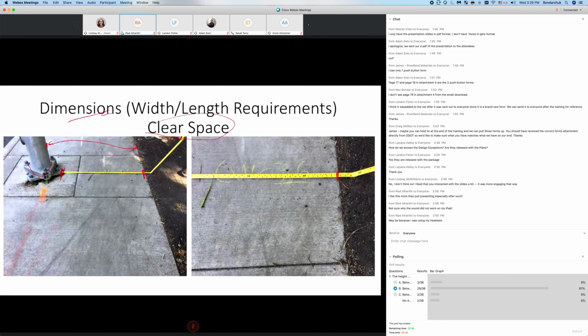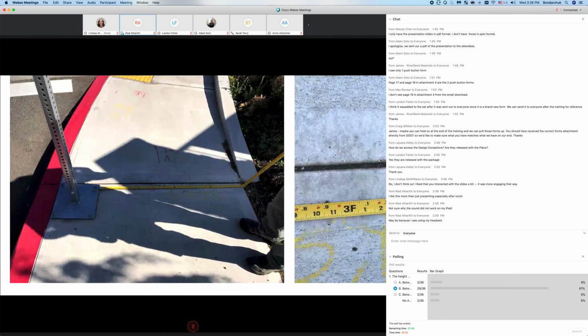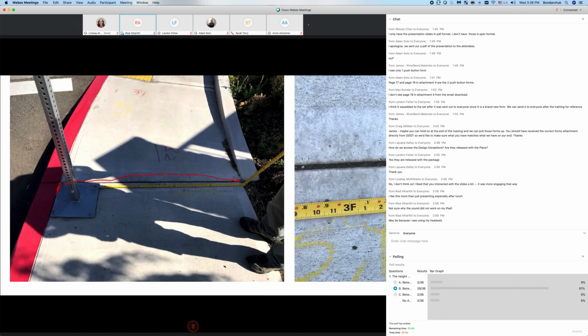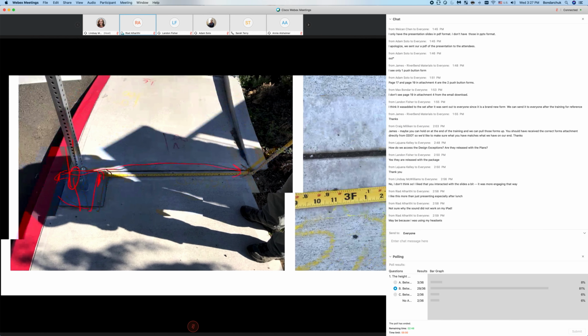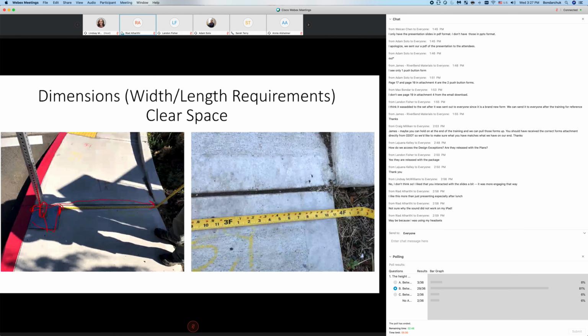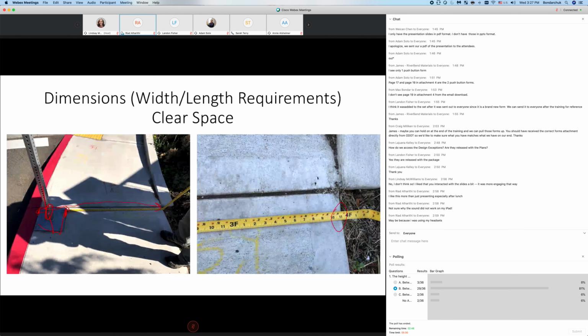This one, it seems, was okay before. And if you look from the back of the curb all the way here, it seemed like we were able to meet the 4 feet. Probably the local agency or the agency who had jurisdiction of the road came and put this plate, put the sign, and there's a lip here that's now restricting the clear width. A better solution would have been if this post was drilled instead of putting this plate, and that would still have met the clear width requirement. I just thought that they needed a little bit here, and they would have made it.